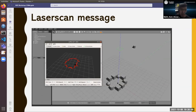The LiDAR constantly rotates and takes the distance between itself and the nearest obstacle. So say the robot is facing this way. Then the data would be all these data points. So one distance, an array of distances. This is the first distance, this is the second, third, fourth, and so on, rotating until the whole